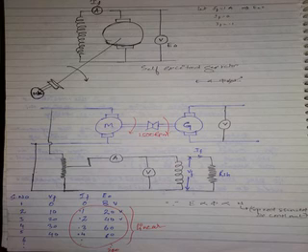So let us think this RSH value is 100 ohms. Let us assume this is 1 ampere, this is 100 volts. So you got a point like that, you will plot a line like this. That is the field resistance line for 100 ohms. Now 100 ohms is the original resistance of the field winding. In the given machine, this is the resistance.